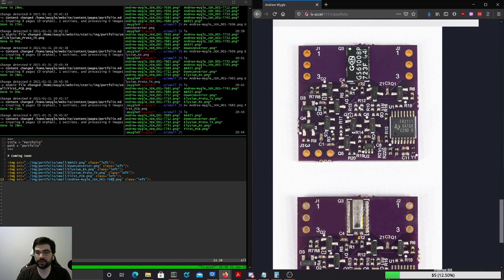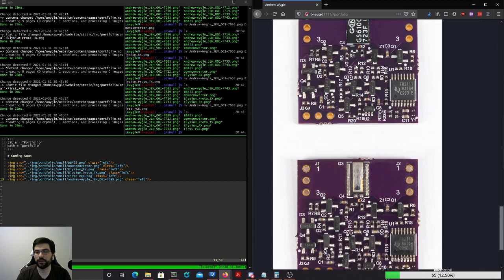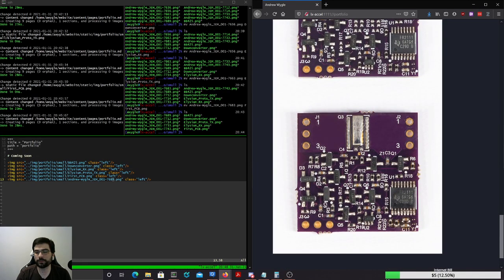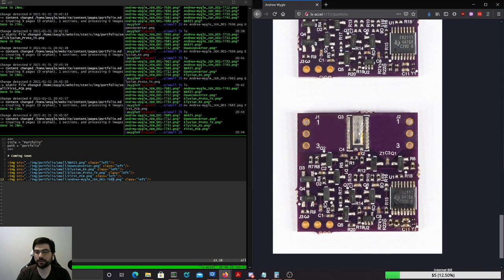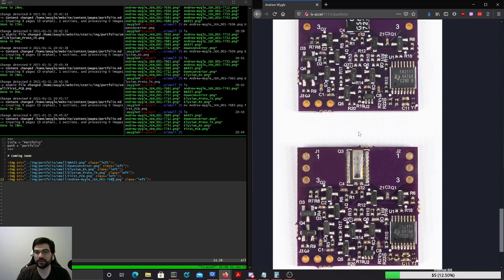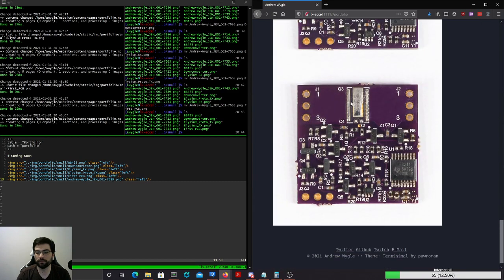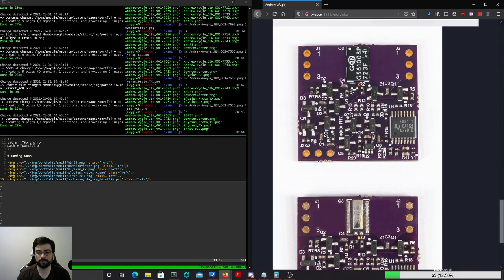So this does everything. It has an oscillator and a whole bunch of stuff. I think the intent for this was to be a charge pump controller. But anyway, the point is that it controls a GaN FET. And then the loading option is, there's this GaN FET, which is from a particular company. Can't remember their name. And then there's another one on the back side, which is a much smaller package. And I wanted to have the option to load for both. So we've got that set up, and that's why they're loaded differently.